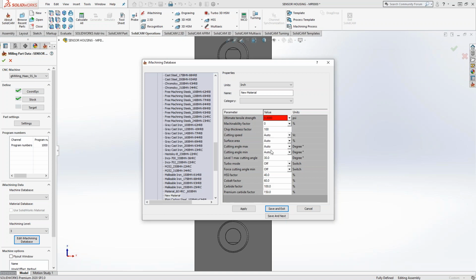You can see there's a lot of auto calculation here, but because this is an optimizing toolpath, you want to put as much information as you can to really dial it in, to get specific on your material and your machine. So if I knew there is a maximum cutting angle for this material, and if I go any more or any less, maybe I'm going to get a ribbon, or dust, whatever. That might be more for non-metals, but generally all this information here is to fine-tune the machining of whatever material you're defining.